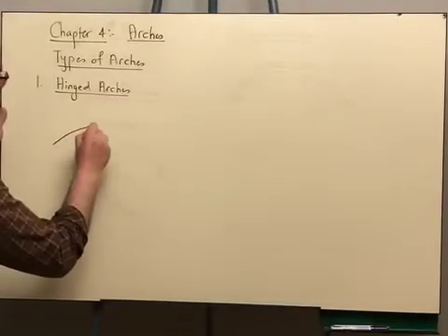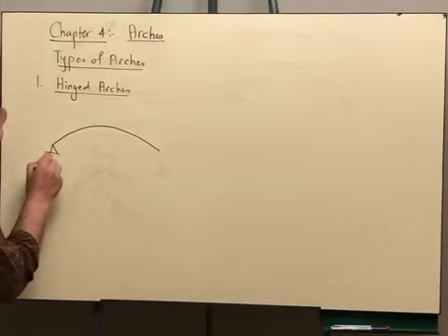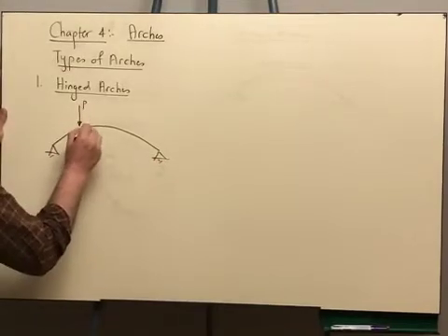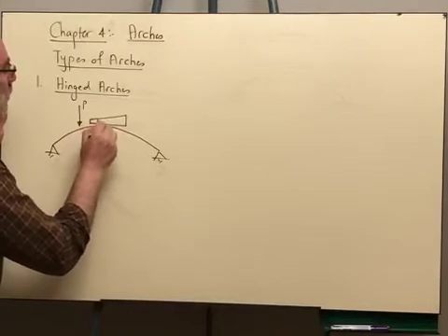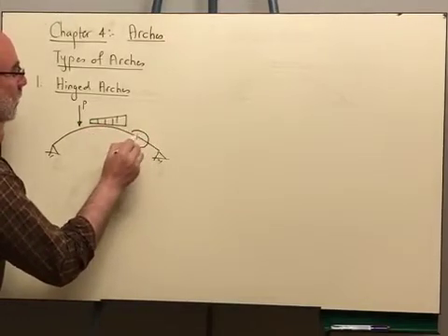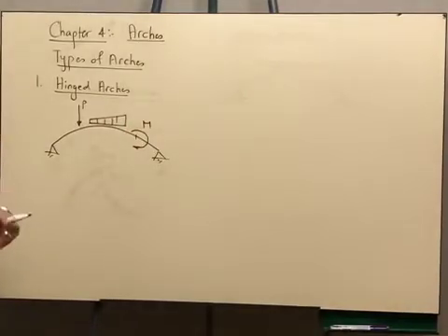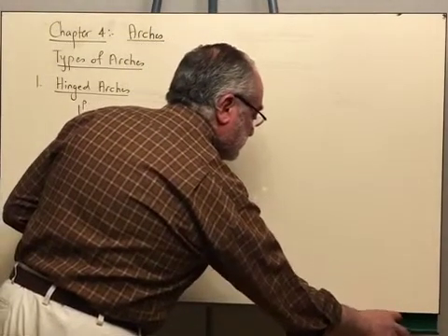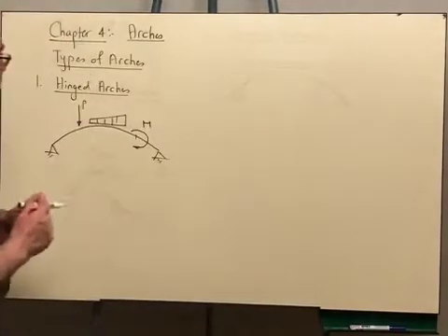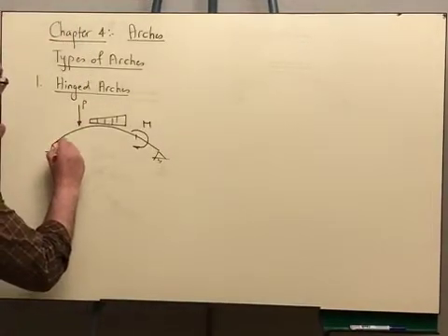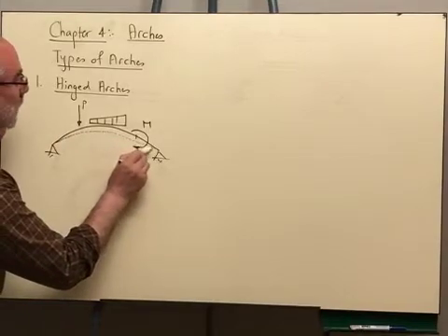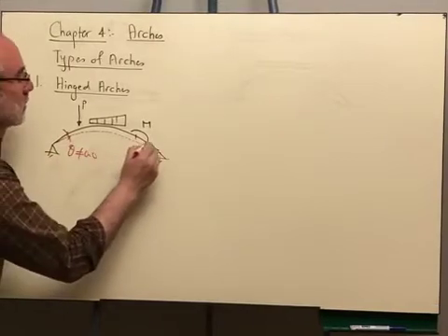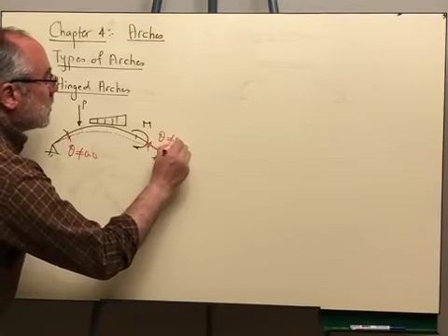Hinged arches, whenever you are having an arch like this, the 2 supports are hinged, it can accept any kind of loading, either concentrated load, non-uniform loading, or maybe a couple, like that. The deformation of the arch will be like this due to the effect of the applied loads. You notice here that you are having angle theta that is not equal to 0, and you are having here angle that is not equal to 0.